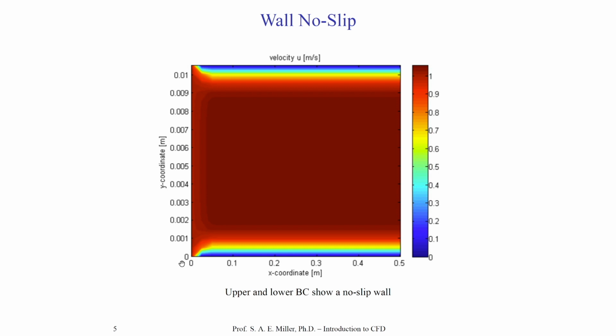Here the flow moves from left to right. The contours represent velocity magnitude. The left side is an inlet boundary condition. The right is an outlet boundary condition. The top part of the wall and bottom part of the wall are where we're setting the velocities equal to 0. You can see within the domain the fluid is relatively undisturbed and moving in the right direction at a relatively constant rate.